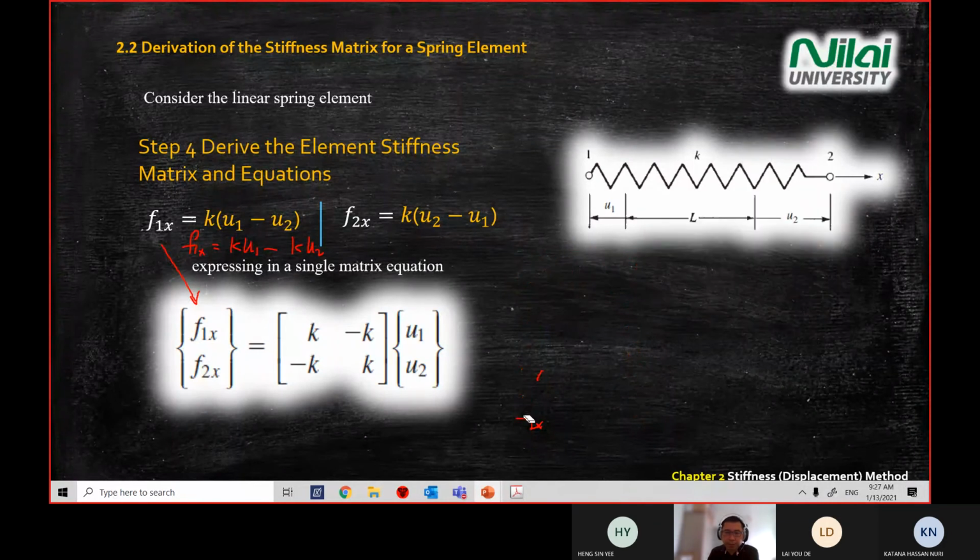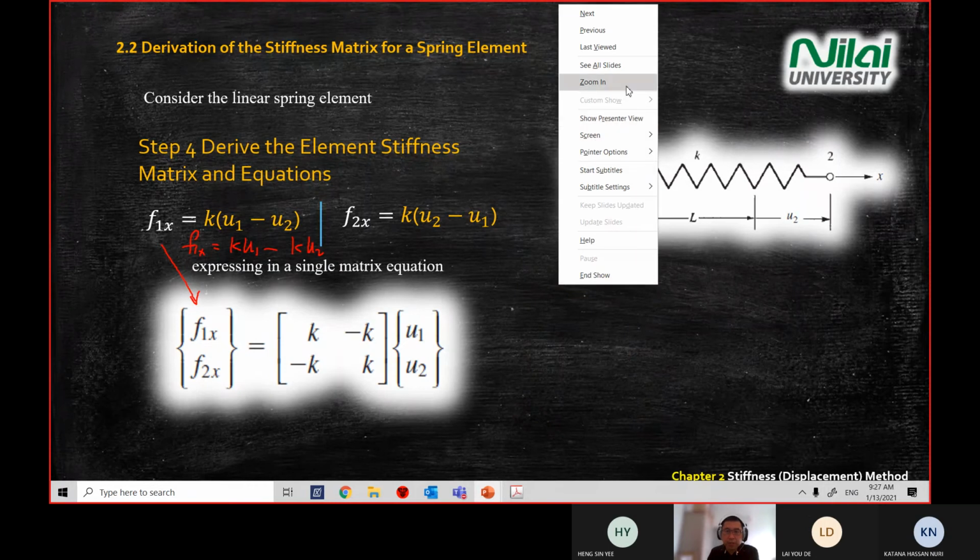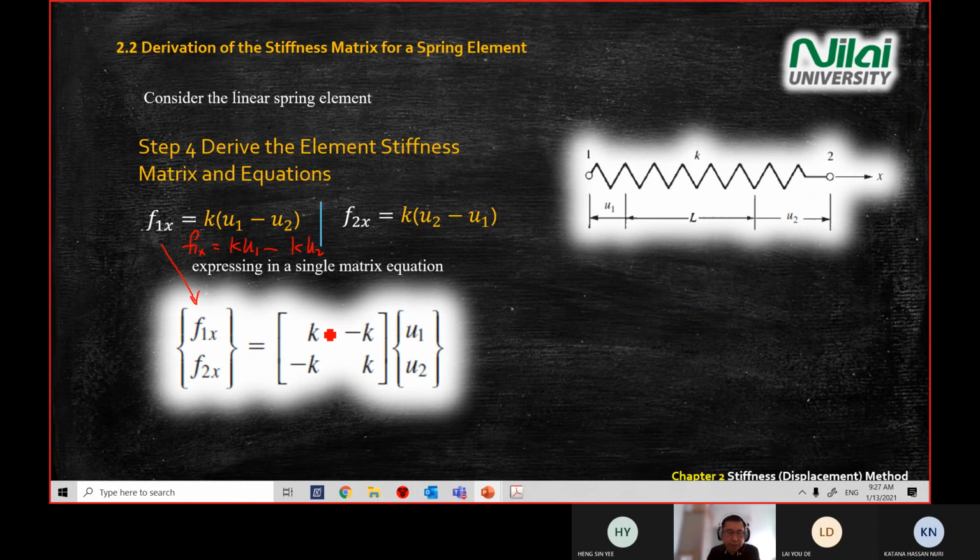All right, I'm going to go into the stiffness matrix now. So in the matrix for your stiffness, which is your K, it will be like a Lego or like a map. So I break my matrix into 4 coordinates. So column 1 here will refer to your U1. U1 means that K and negative K both relate to U1.